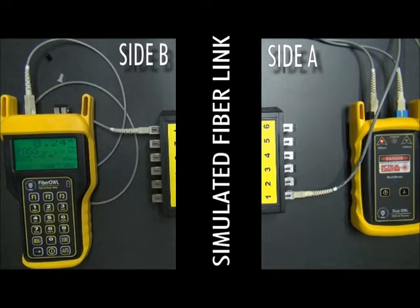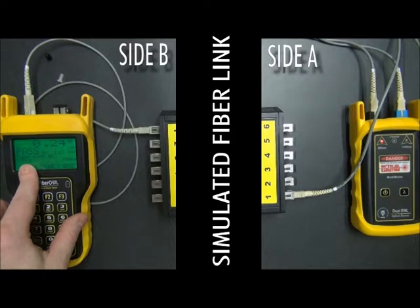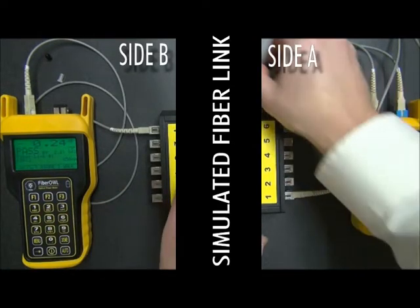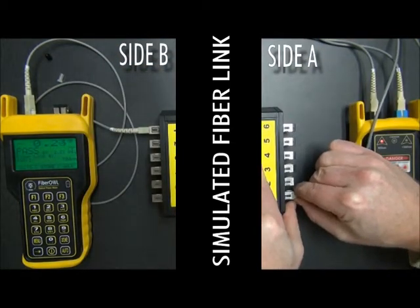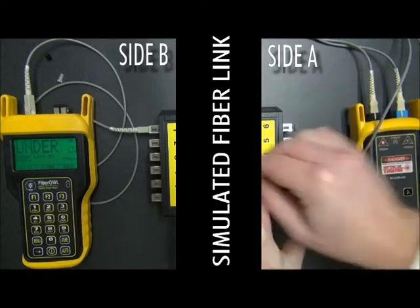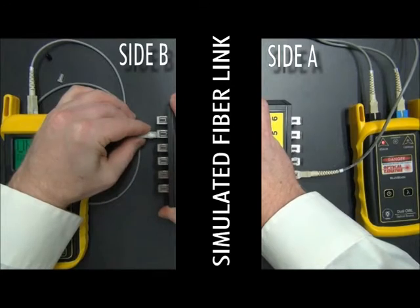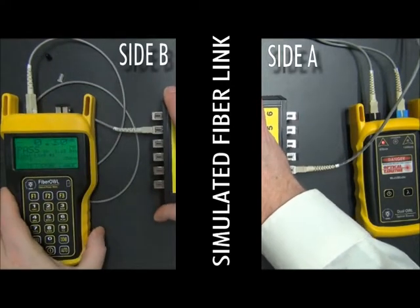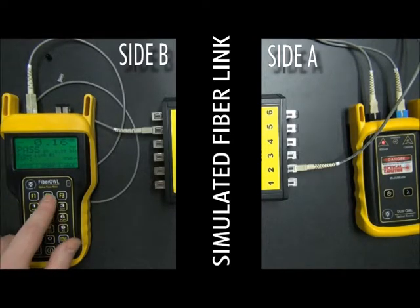Okay, now what we need to do is connect into fiber number 2. Notice that it's showing you fiber number 2 here, so it's ready to take a reading for port number 2. So we simply disconnect and reconnect to port number 2 on this side, port number 2 on that side. As you can see, we have another loss reading here. So we're happy with this result. It's passing. We simply press F2.